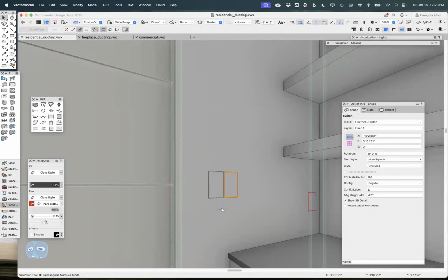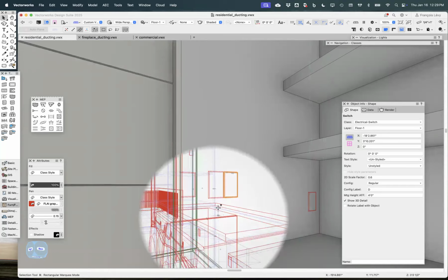So yeah, these are relatively lo-fi models. It's not that they're going to solve the design problem of where to put your switches. Vectorworks will happily let you put a switch right next to a pocket door pocket. I created my own symbol for a 3D switch years ago just for that reason, because I can see myself making that mistake.